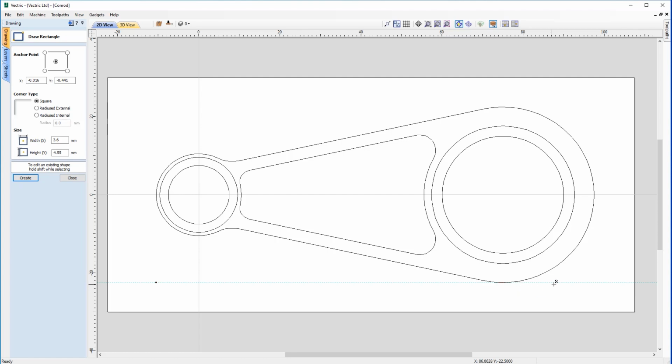If I just hover my mouse pointer over to that, I can click on this and you'll see that I've got the corner which meets the intersection of each side of this outside vector. I can then click on it and drag up to the opposite corner now, and you can see the black dot has appeared for me to snap to. If I let that go, now that is the rectangle that is around just the edge of our vector. So it touches all the edges of our outside vector here, which is exactly what we want.